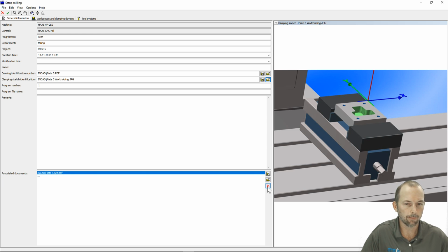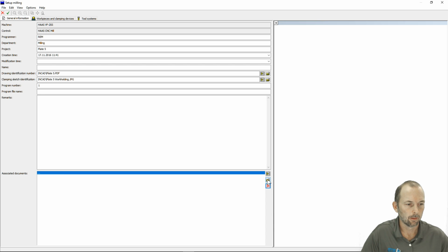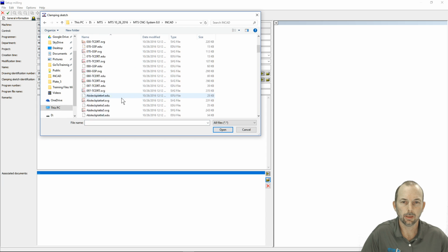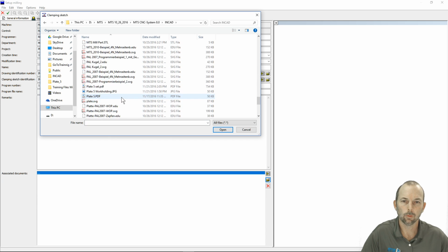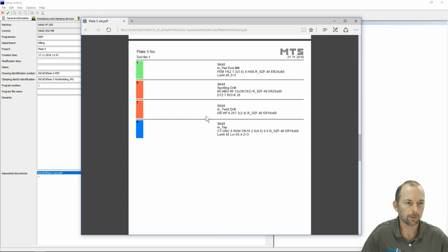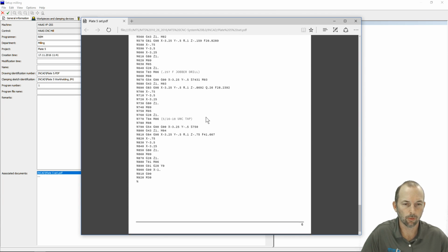In order to do that, we'll get rid of this guy and we'll say File Open. And we have that guy sitting in InCAD as well. We're going to say Plate 5 Set. So now we have this PDF that we've created that lists our tools and contains our CNC program.